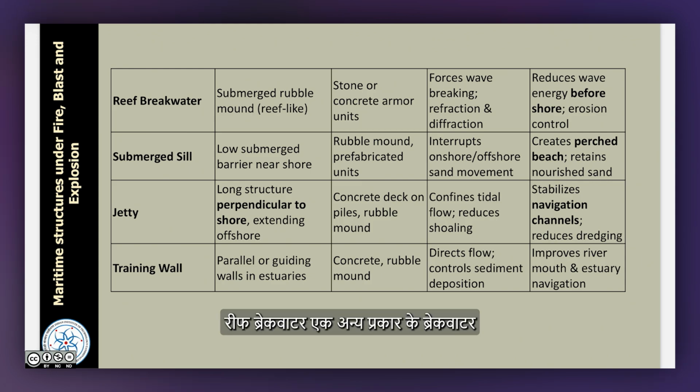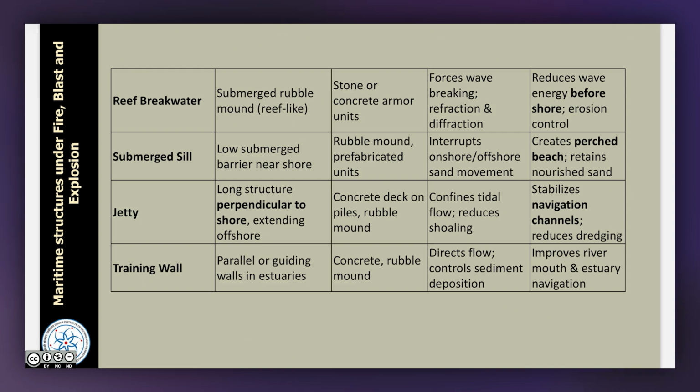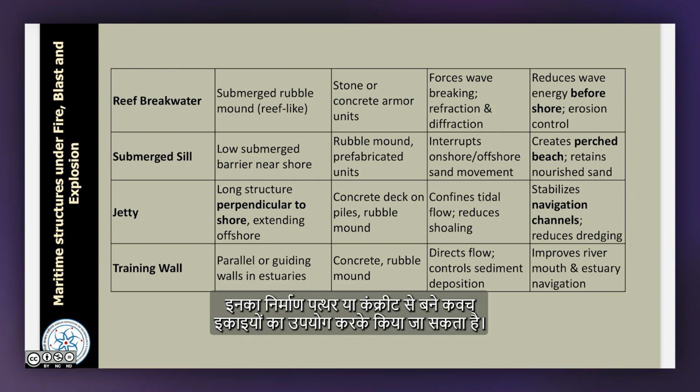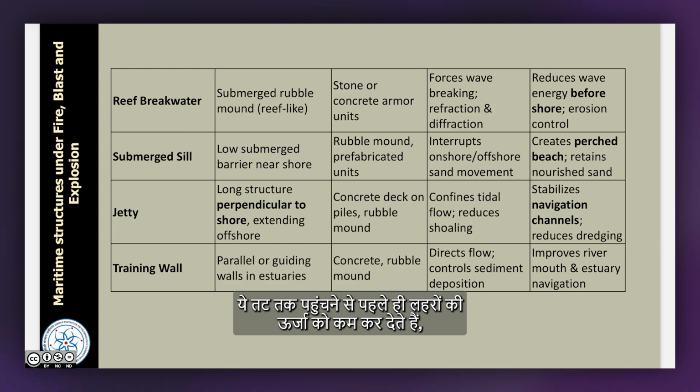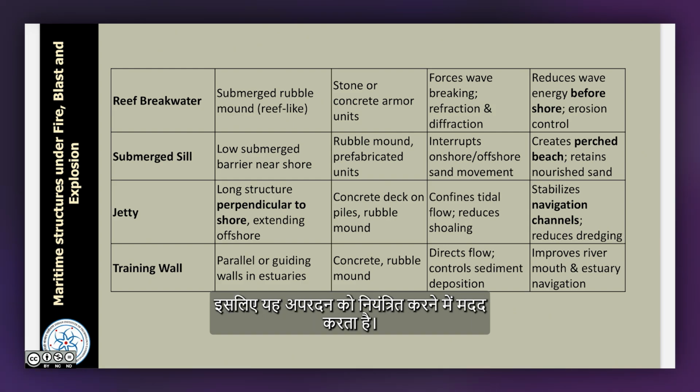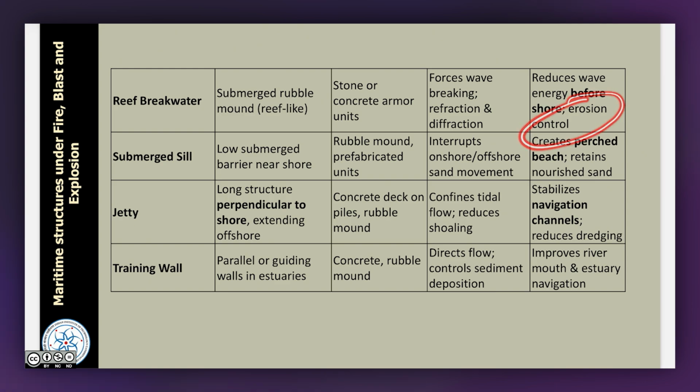Reef breakwaters are another type of breakwater, which are submerged rubble mound systems. They can be constructed using stone or concrete armor units. They help in breaking the wave forces by refraction and diffraction. They reduce wave energy before it reaches the shore. So, therefore, it helps in controlling erosion.